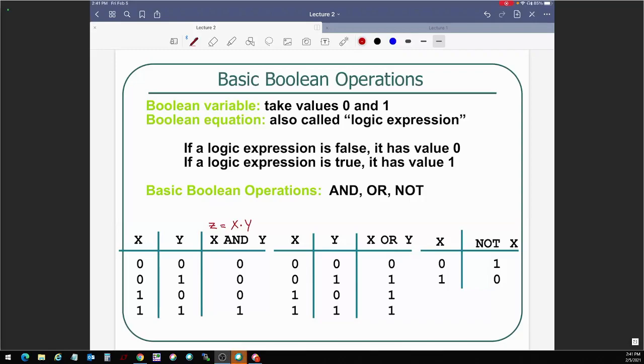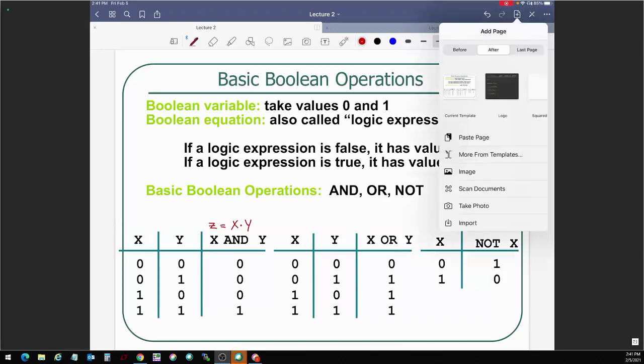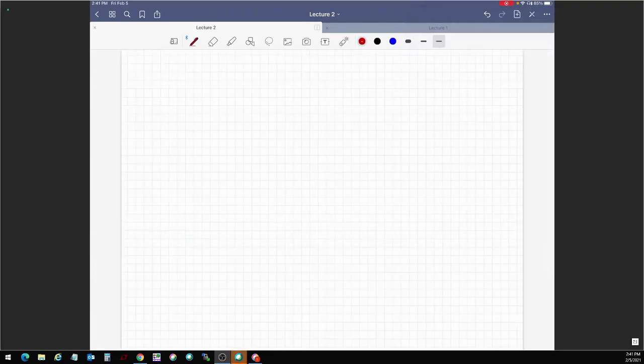Right. So here, since you guys raised the topic of convolution, you will see more of this in signals and systems, but let's just take a detour here. So suppose you have some system, right? This is a black box. I don't know, it could be a circuit. It could be a room. It could be anything that you're trying to analyze. The first requirement for convolution to work is that it has to be linear and it has to be time invariant. We call those systems linear time invariant, LTI systems.